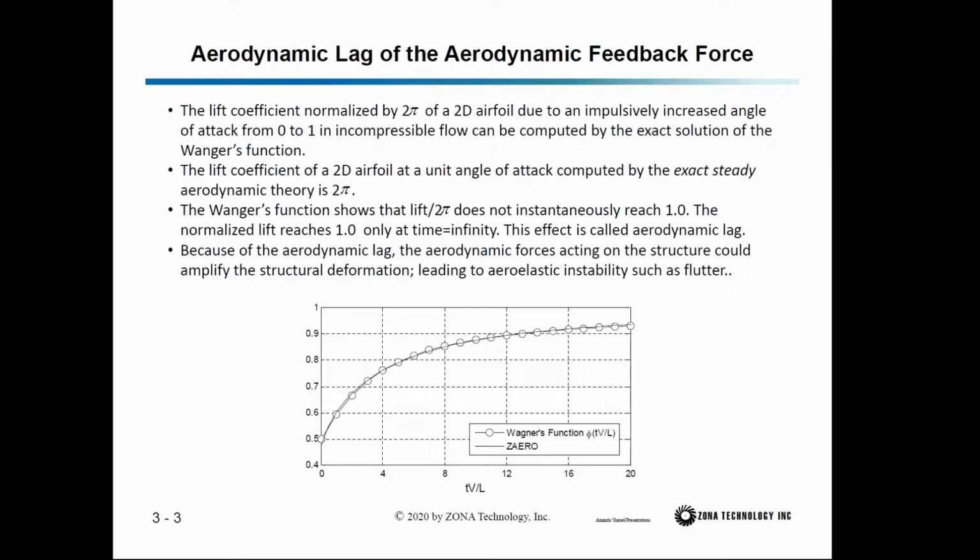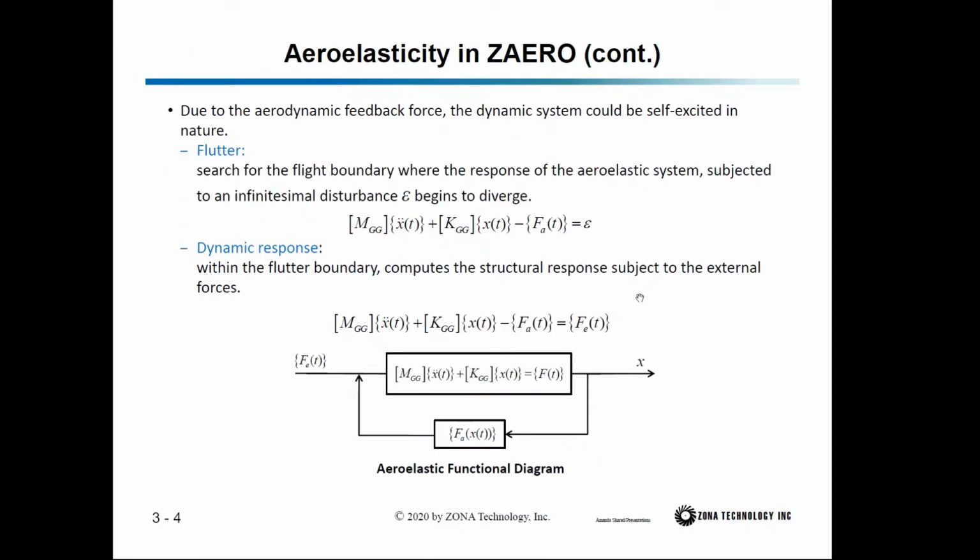Because of the aerodynamic lag, the aerodynamic forces acting on the structure could amplify the structural deformation, leading to aeroelastic instability, such as flutter. For example, if you have a structure moving up, and due to the lag effect, the lift could also be acting upward, which amplifies the structure motion.